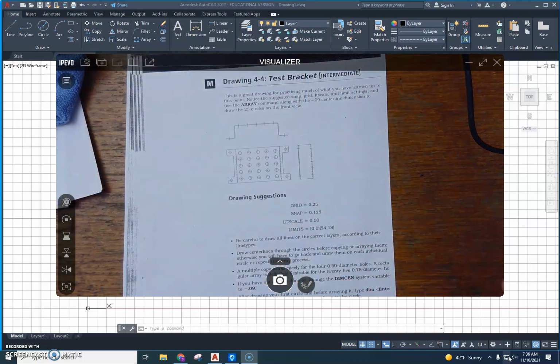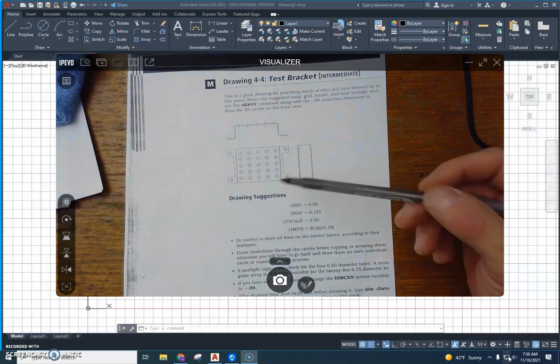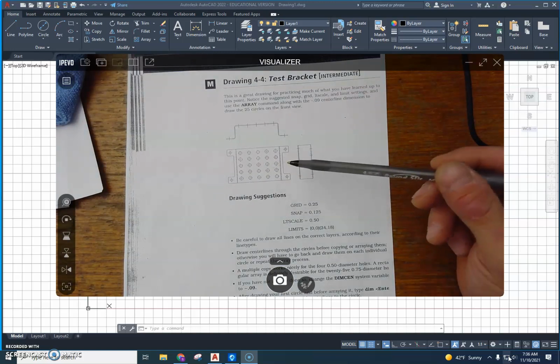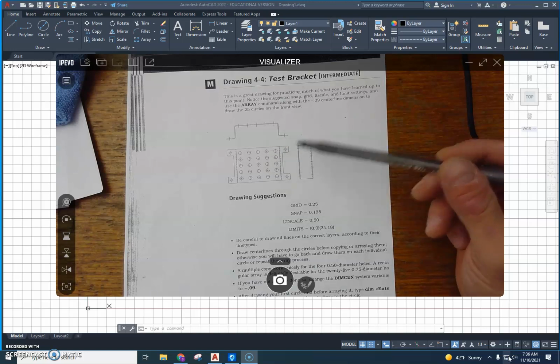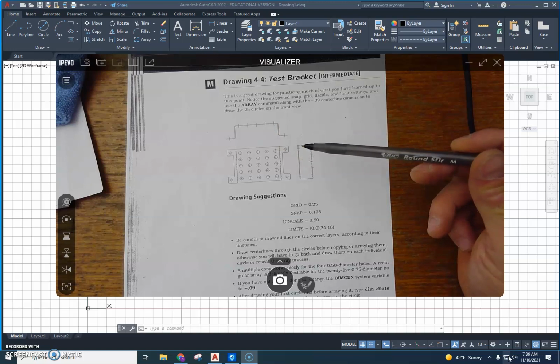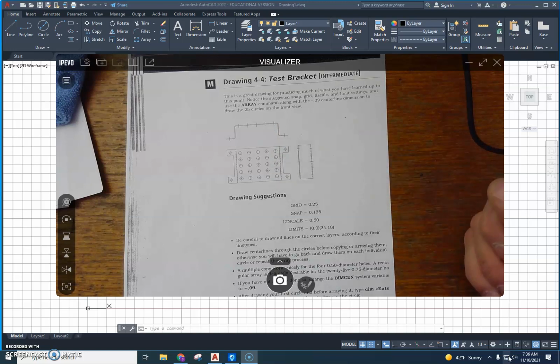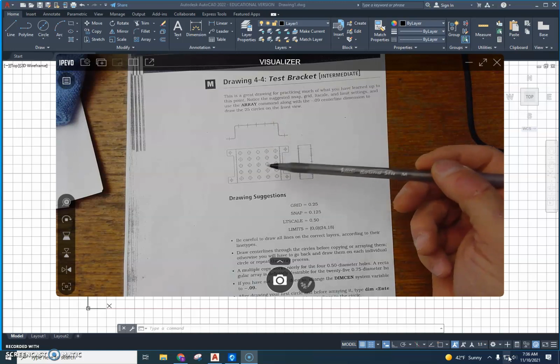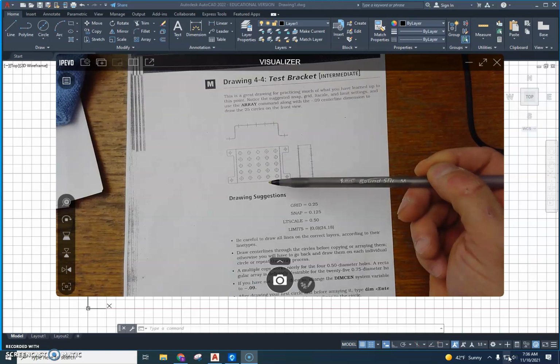So it's called a multi-view drawing because these are 2-dimensional drawings with an x-axis and a y-axis. You don't get to see all the depth. There's no z-axis on these, so you have to give it more than one view to convey all the information you need so somebody could actually make this. This is what they're for. They're technical drawings, giving you the information you need to go fabricate this or make it.